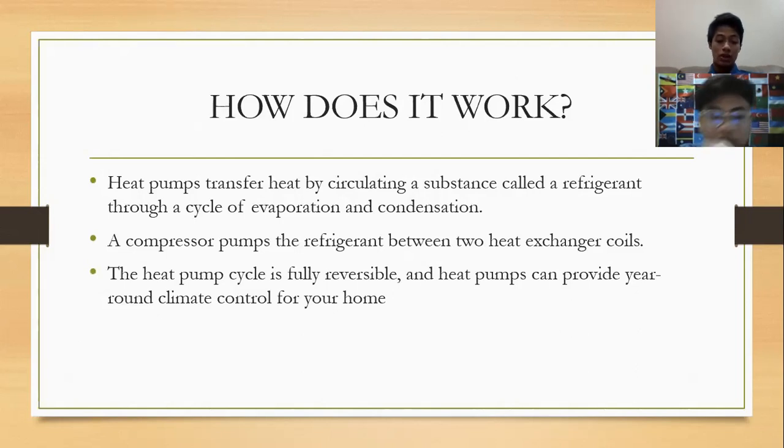The condenser or evaporator fan will not run during the defrost mode. The indoor fan will continue to run during the defrost cycle. In cooling mode, the cycle is similar, but the outdoor coil is now the condenser and the indoor coil is the evaporator. This is the familiar mode in which air conditioners operate.